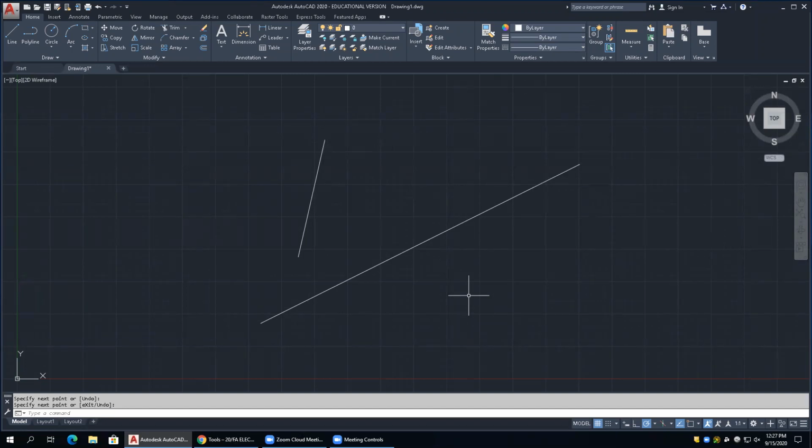You can have more than one boundary edge, certainly, and you can have more than one object to extend. So extend is noticed up here. Right now, mine says trim. Buried underneath trim is the extend command. So I'm going to go to extend. You can also type in its alias, which is EX. Okay, so if you like typing, EX, enter.